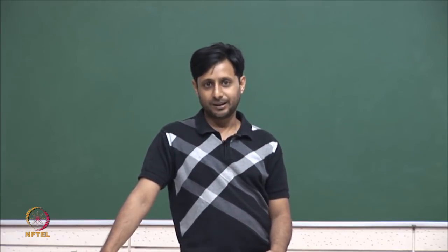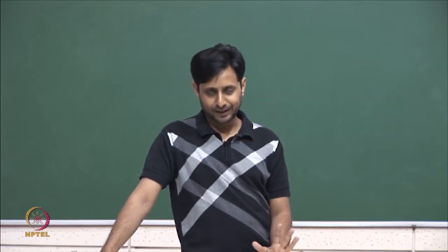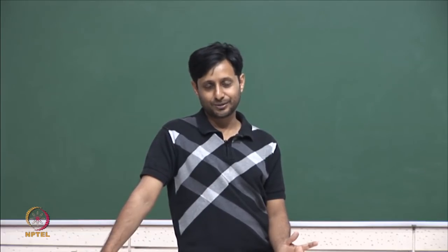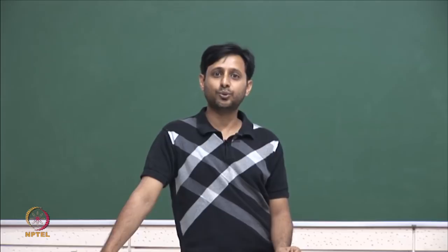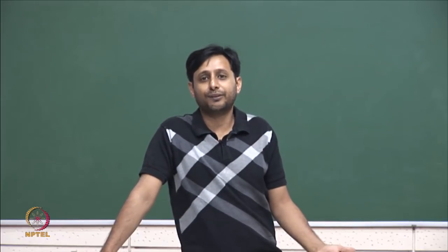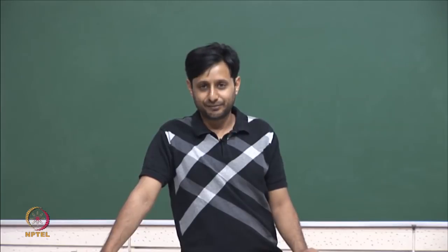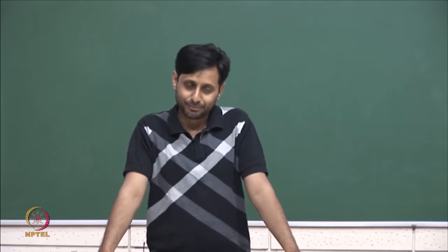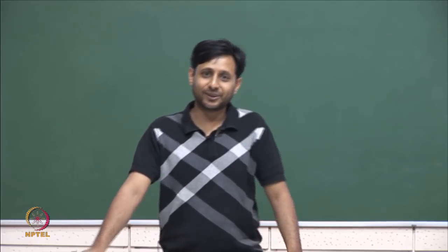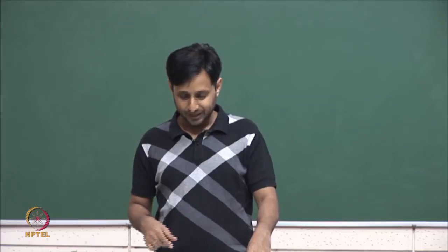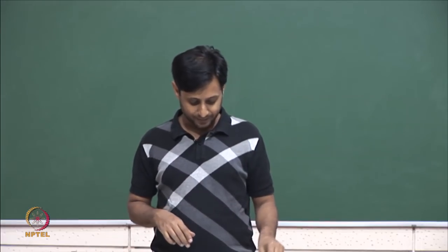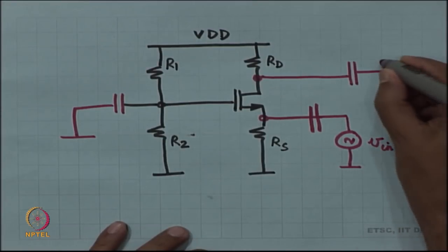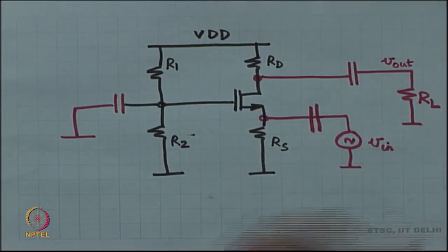So, you can do that, that is, so the final answer is you can apply signal at the drain and watch the output at the source, but if you do so, you will not find any gain coming out of the amplifier. Okay. So, that is the answer. So, do not do it, basically do not make a circuit that is not very useful. So, this is the useful circuit where I apply input at the source and watch the output at the drain.